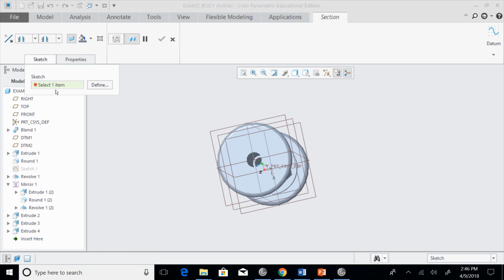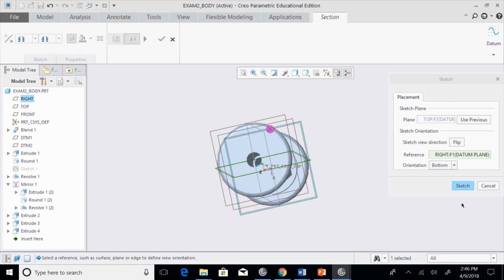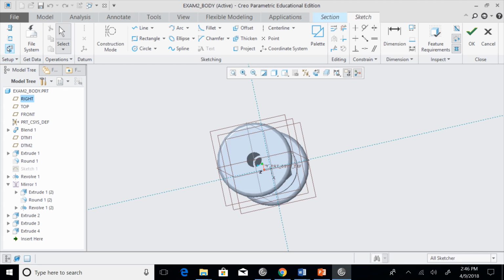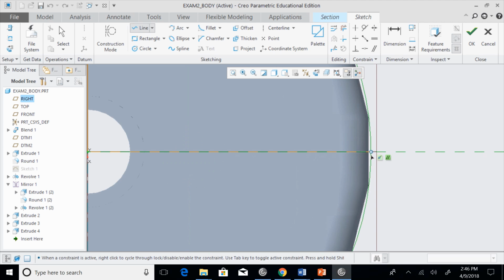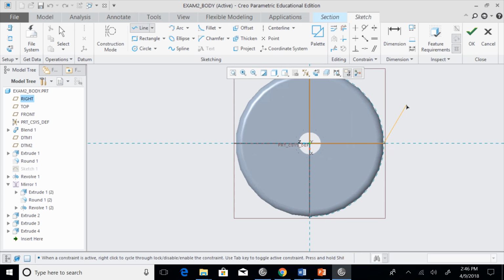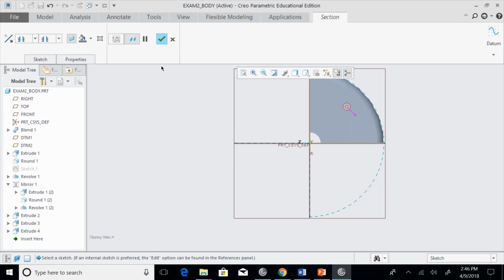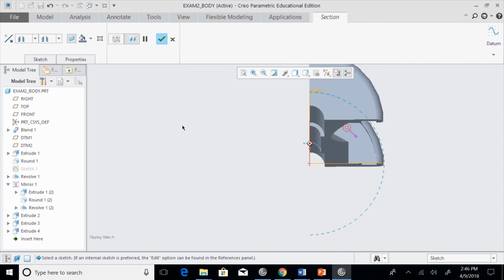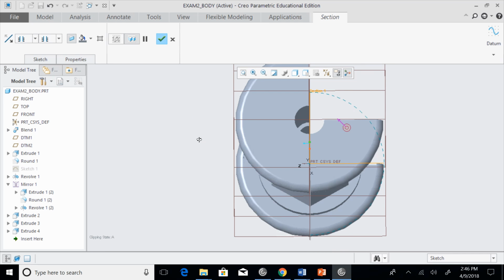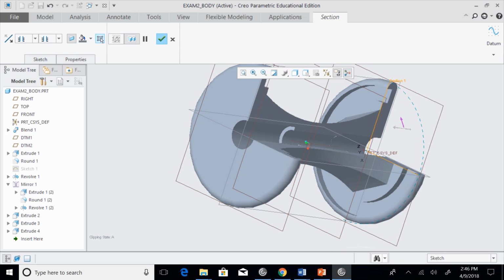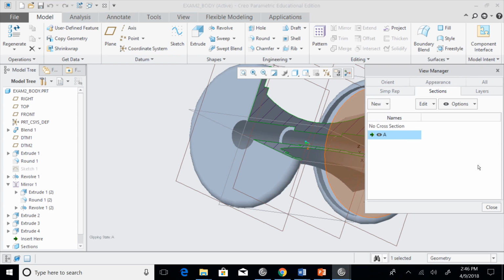Sketch. I'm going to look at it from the top to make that cut. Sketch view, select line, just draw a line from there, from the top to the center, back out to the side, escape, okay. We want the 3/4 and not the 1/4, so click this button to reverse it. We also want hatch pattern, check.